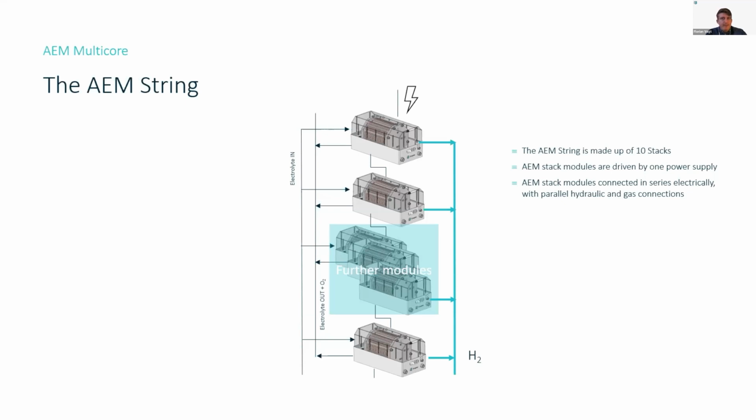So the AEM string is made up of 10 stacks. The stacks are driven by only 1 power supply unit. And basically, this is then 1 electrolyzer for us. They are connected in series electrically with parallel hydraulic and gas connections.